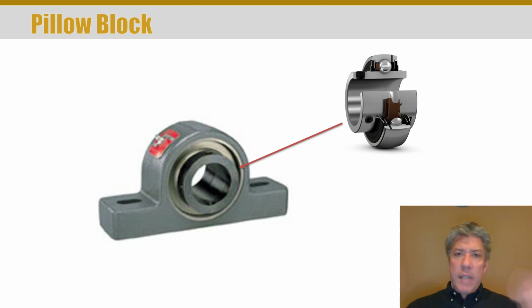So if you're going to have a live shaft, that shaft has to rotate relative to the frame, but the frame, once it's welded, is not all that precise. It's not all that exact. So you need a bearing that can be self-aligning, and what's typically used on a go-kart, at least, are bearings more like this.